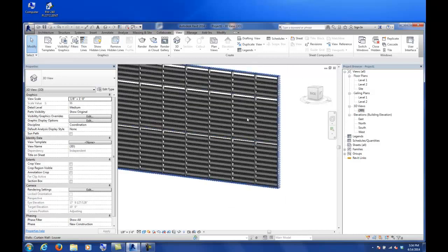And if you already have that set up as a parametric panel, you could either set it up as a storefront system and make it easy, kind of equal everywhere, or you could also put that in a curtain wall and then divide it up in whatever pattern you want to match probably your mullions behind, or whatever you want to do. So you want to model this as a separate curtain wall that's kind of floating in front of your other facade. Okay. Does that make sense? Mm-hmm. So change your profile blade however you want.